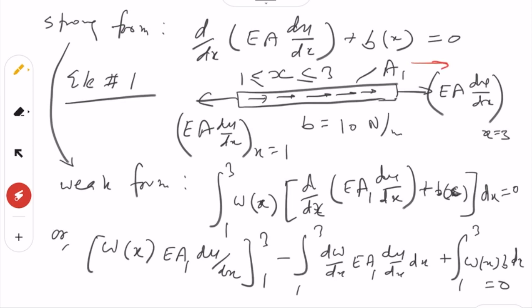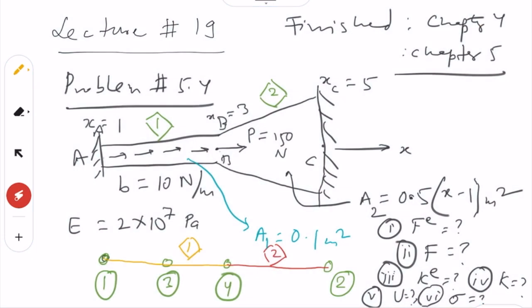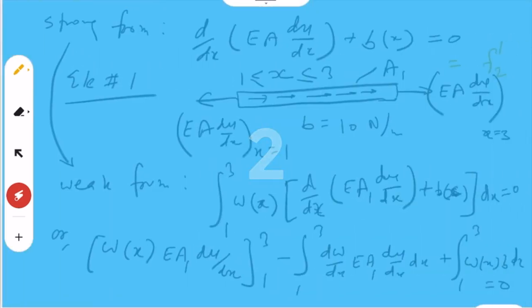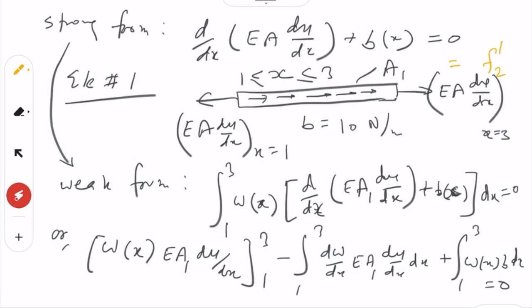If we take the force F, we are calling it F of element 1 at node number 2. It is not node number 2 because, so we are not confused, here the global numbering is 1, 3, 4, and in local we are writing 1, 2 and 3.